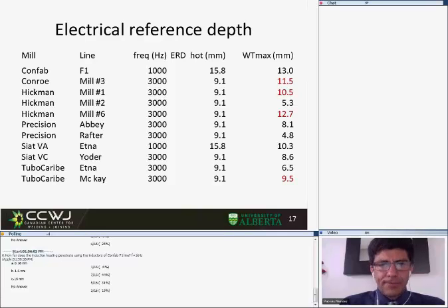It's not a huge difference, but what this means is that in this case, we need heat conduction to homogenize the cross-section. And if we depend on heat conduction, the residence time is relevant, and if the mill moves faster, it can get us into trouble, because we need the heat conduction to help us reach the other end of the tube.